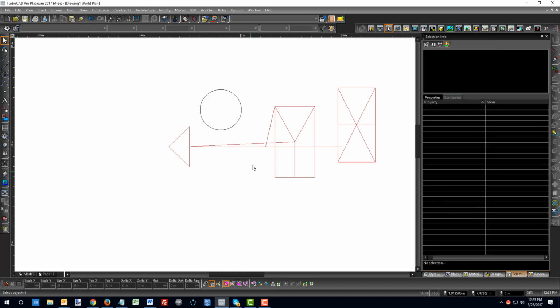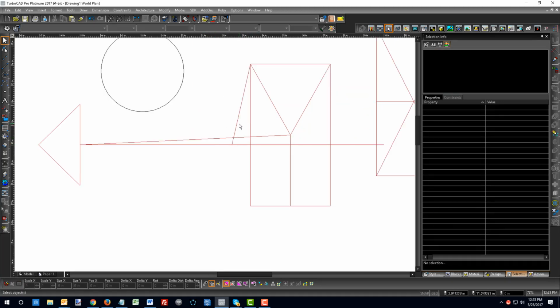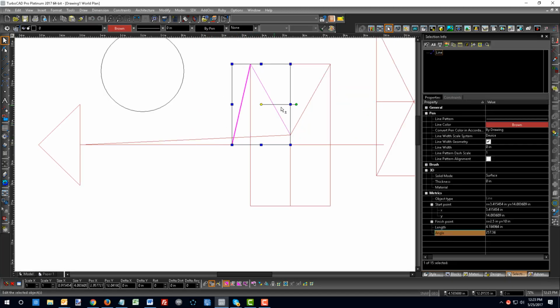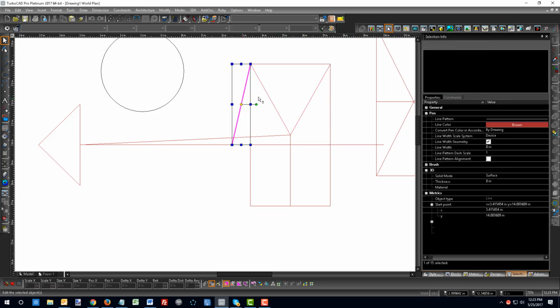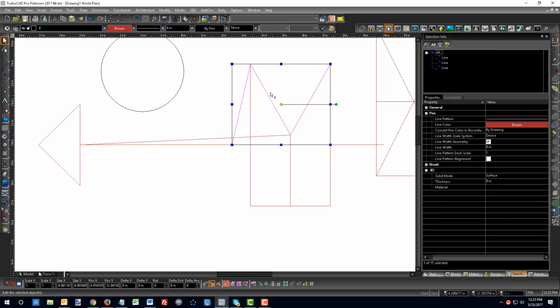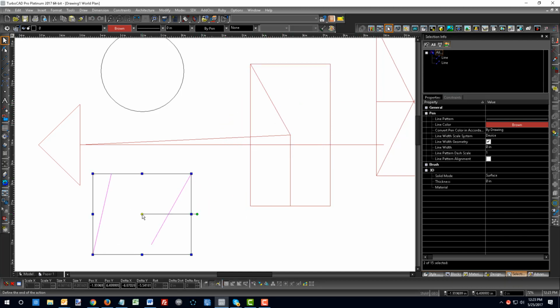And if I want to select multiple objects, I can hold the Shift key down and continue my selection mode. This is actually a toggle. Notice a little plus minus indicator here. So as I'm selecting or reselecting objects, if they're selected, they're magenta color, and if I want to reverse my selection of that particular object without deselecting these other ones, I can just click on it again and now it's unselected, and I can move just these two items out of the way.